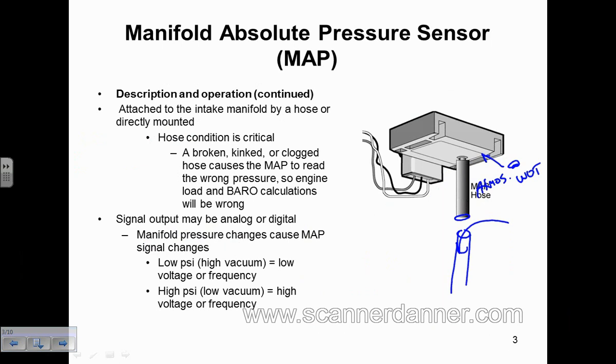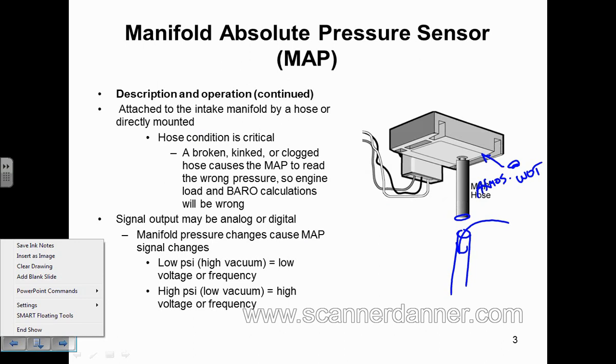The other day we were working on a car in the shop and we had a MAP sensor connector that was unplugged, reading high voltage all the time. That car would not idle, would it? It would not idle. Now that car's got other issues too, but that was a factor with this MAP sensor. So you can have that effect. That's pretty common on a vehicle with a MAP sensor. Pay attention to that hose.